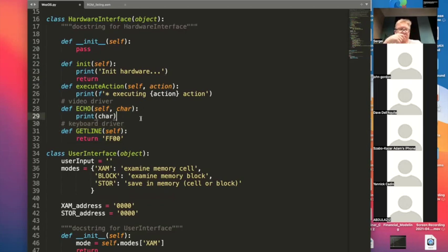But what is very, very interesting and specific for Apple One and the Woz operating system is that it has two distinct functions here that are connected to hardware. It's echo, so it prints some char to a terminal to display, and it provides this function to all the other programs of this operating system. So if we write something like hello world, as we did in our Tuesday webinar, we use this function. We don't really need to understand how this terminal is working. We just call this function using its address, and that's it. Only the char is used, and it uses it from register A.